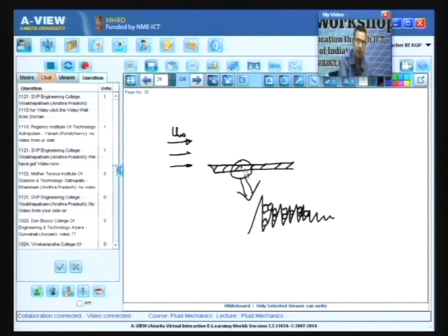So, the fluid in contact with the solid understands the effect of the wall, and if the wall velocity is 0, the fluid velocity is also 0, and that is known as the no slip boundary condition. Now, let us try to draw the velocity profiles at a given section. At the wall the velocity is 0 because of the no slip boundary condition. Now, next if we come to the next section